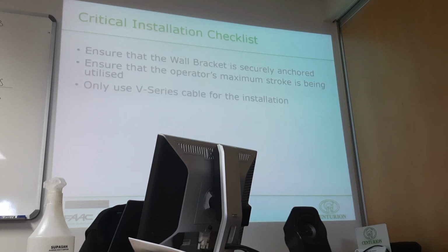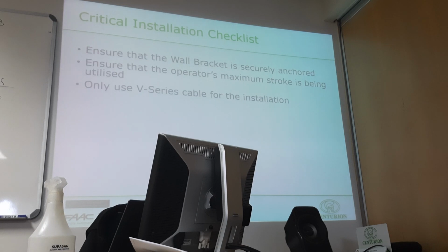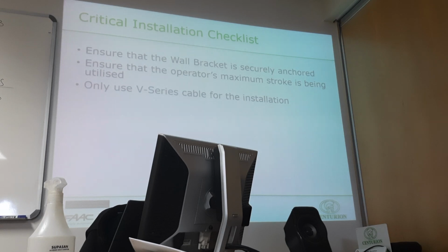Why would I want to do that? Because if you look at this one, it doesn't sit exactly straight to the top one. So I would say, it's easy, let me just turn it 1 more back or 1 more forward. But it's already on its maximum, so I couldn't turn it. So if I want this one flush with this one, I have now to move my bracket. You can't see now my gate bracket. I have to move it here now for me to have more flexibility to open and close it a bit. So that's why I would say 1 or 2 turns. 2 turns will be the best because then you've got some flexibility on making sure that the gate stops exactly where you want it to stop in its closed position.